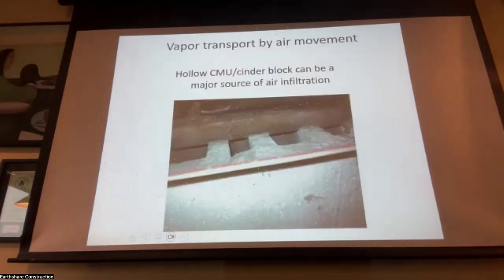So when you insulate the foundation, you want to come across over to the sill and seal to the rim joist and up to the floor, not just to the top of the block wall. I see that all the time. A lot of times in a basement, if you reach up over the top, you can feel, you stick your fingers down in the blocks, and there's foam on the rim joist and foam on the wall, but nothing on the horizontal, because they couldn't get to it.